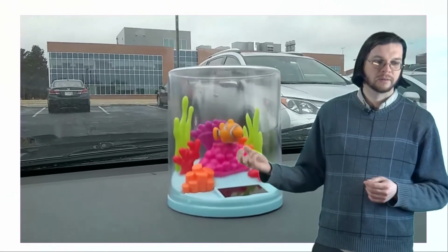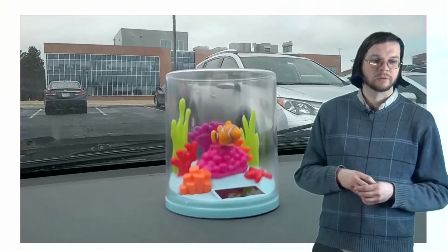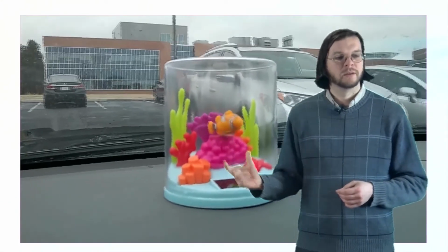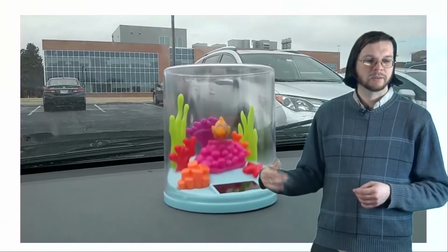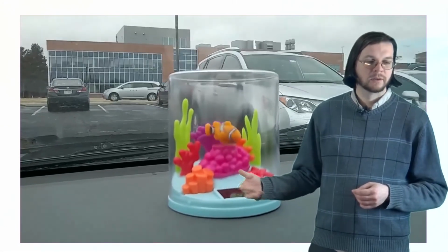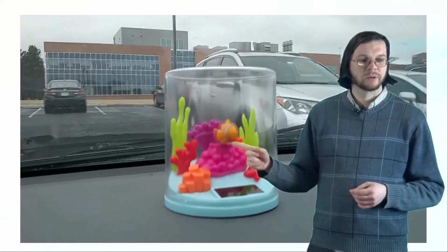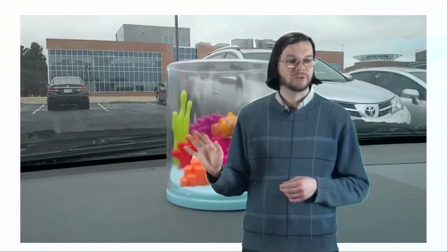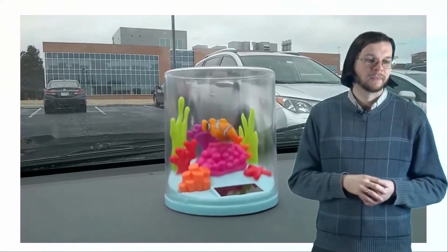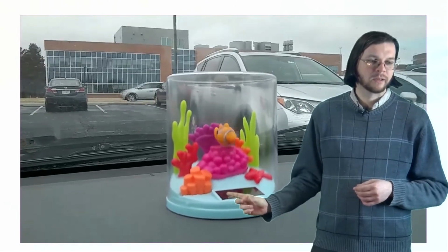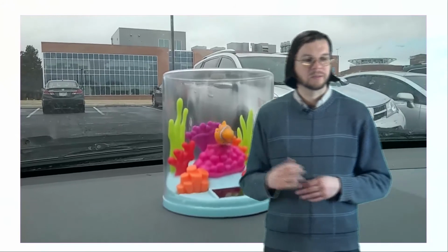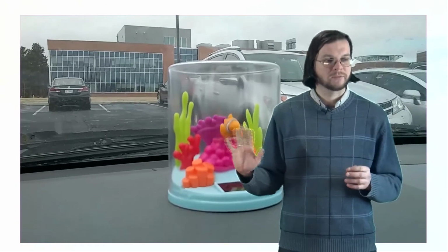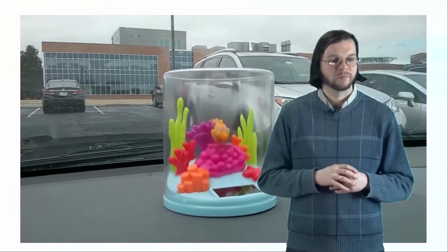And so what ends up happening is that very naturally, if there's sunlight, that causes this fish to vibrate back and forth. So it's sort of hanging by a thread. I don't know if you can see the thread hanging from the middle of the thing. But the sunlight puts a little bit of energy into the circuit, and then that energy oscillates back and forth, and in the process it causes this fish to kind of wiggle back and forth. So this is kind of an ingenious toy because it doesn't need any batteries. It only needs a slight amount of energy from the sun, and what they've done is that they've tuned the capacitance and the inductance of this thing to make sure that it's about at the right frequency to get this little fish to vibrate back and forth.